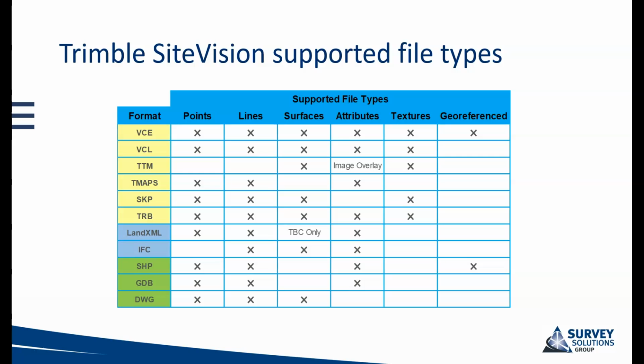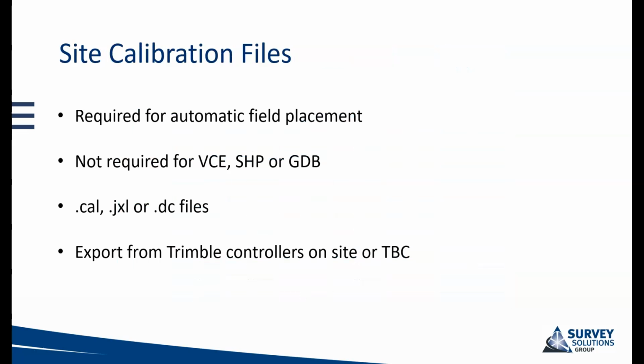Lastly, DWG files from Autodesk. If it's DXF that you have, you can upload these to TBC and use the SiteVision exporter. So we briefly touched on it, but site calibration files, these are important if you would like to have your data automatically positioned in the field.